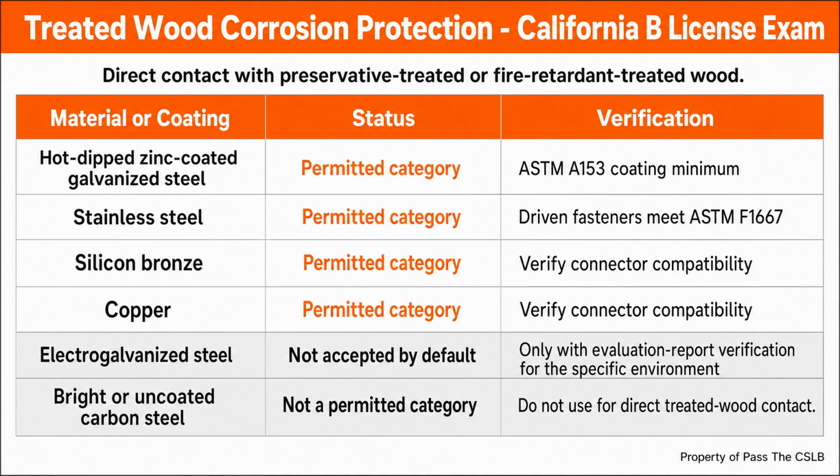This is where sequencing saves money. Review hardware conflicts before rough plumbing, electrical work, or close-in creates a forced choice. Confirm the connector model and fastener schedule during layout. Inspect before concealment. A few minutes of coordination can prevent removal of finished work and replacement of damaged hardware.